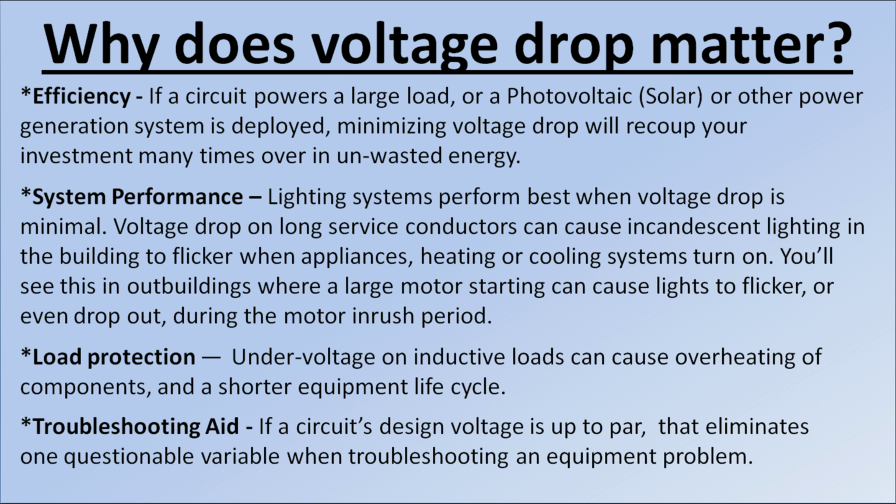Why does voltage drop matter? Efficiency. If a circuit powers a large load, or a photovoltaic or other power generation system is deployed, minimizing voltage drop will recoup your investment many times over in unwasted energy. System performance. Lighting systems perform best when voltage drop is minimal.